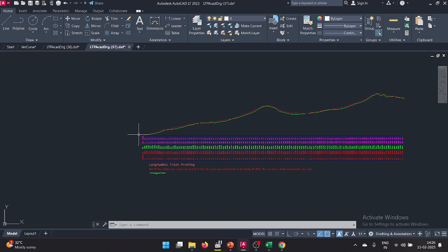Normally we want to ensure the perfect level so that riding comfort will be there. If there is any undulation, there will be more vertical acceleration, and the comfort will not be there. So it is the responsibility of whoever is maintaining the track to ensure the longitudinal profile of track without any undulations. For that, it should be checked periodically and the longitudinal level corrected.